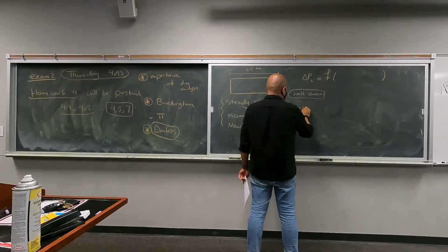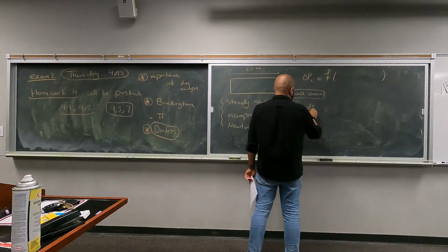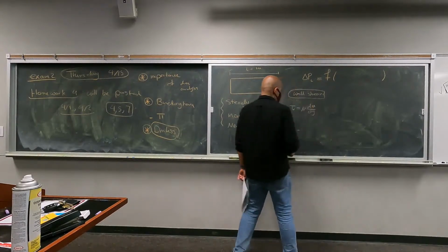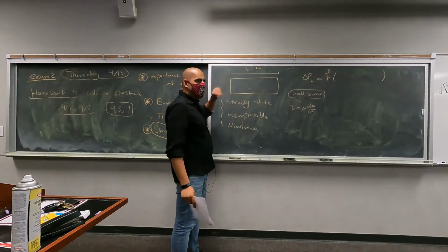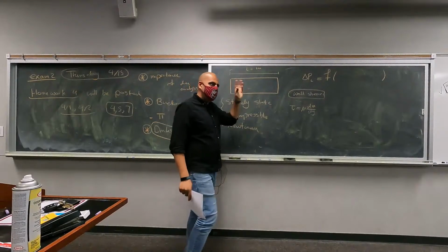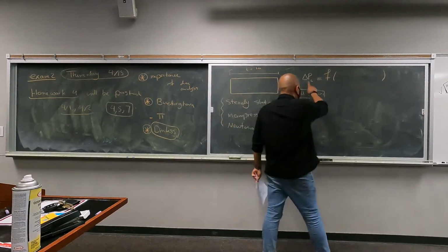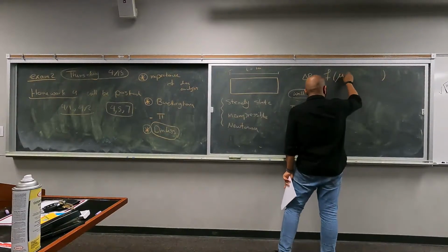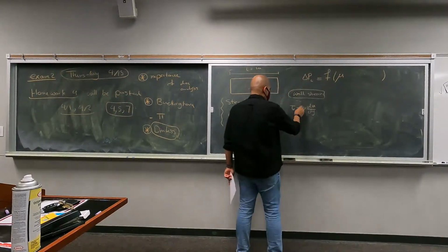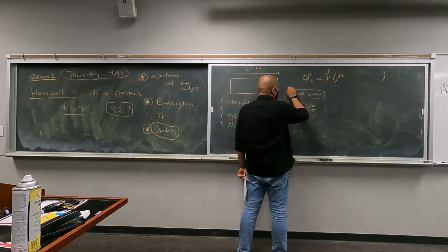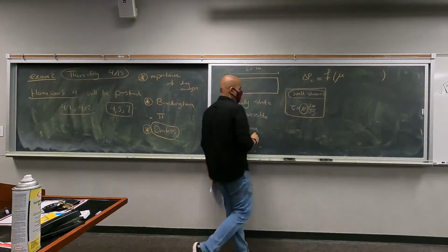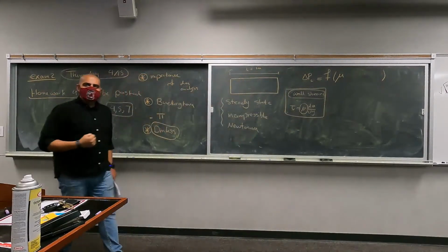Tau, mu du/dy, right? We have 2 walls here, flowing inside the pipe. The radius is small, so which essentially means that your wall shear is going to be very important, which means that your pressure drop is definitely a function of viscosity, right?